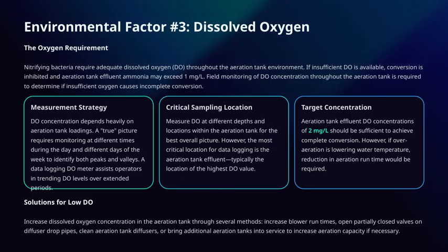Using a data logging DO meter can be very helpful here, as it allows us to track trends over extended periods and make informed operational decisions. Now, where should we measure DO? Ideally, at multiple depths and locations within the tank to get the best overall picture.